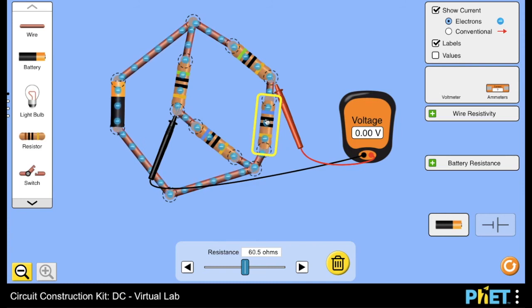Then by connecting that resistor in a circuit and using certain combinations for R1, R2 and R3, you are going to establish a value for Rx by using the theoretical method Rx equals R2 times R3 over R1. But in that case, there are going to be multiple possibilities for the values of R1, R2, and R3.